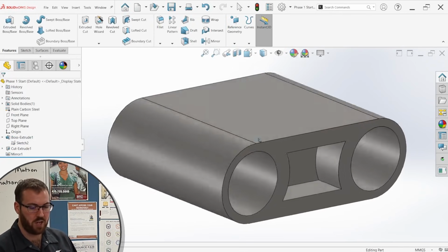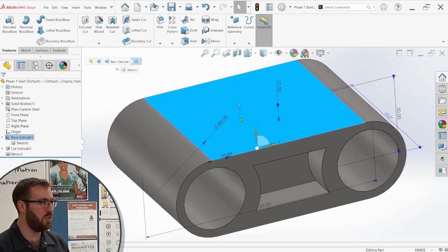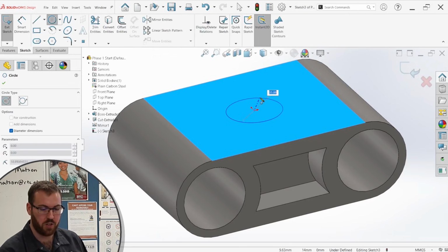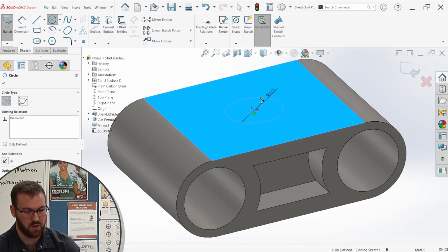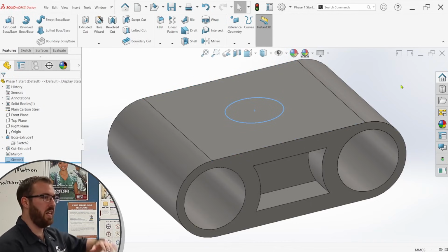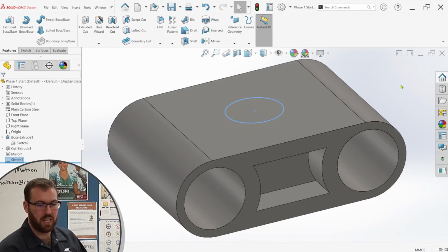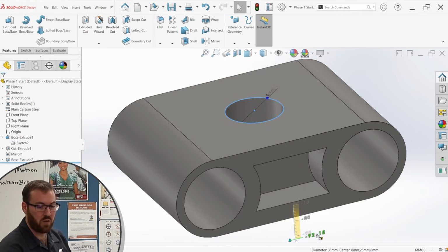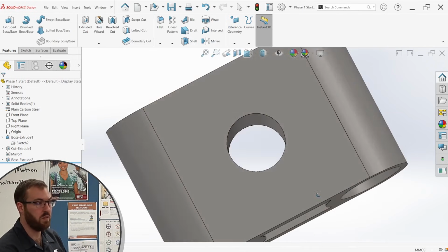And we're on the home stretch now. This next one's pretty easy. This is just a through hole. I'll create a separate sketch, again taking advantage of all of my tools here. It's 35 millimeters. And I've got a pretty clever one for this. Instead of going in and starting a new feature, I like to use Instant 3D sometimes. You've got to be comfortable with this to do it, but if I just click on this sketch contour, an arrow pops up. If I click and drag it up, it creates a boss. If I click and drag it down all the way through, it creates a hole.